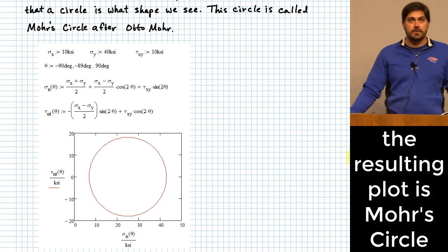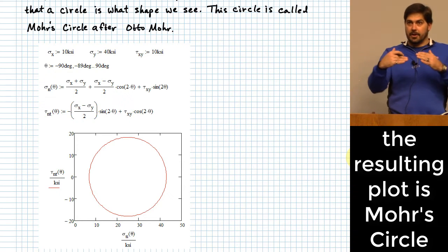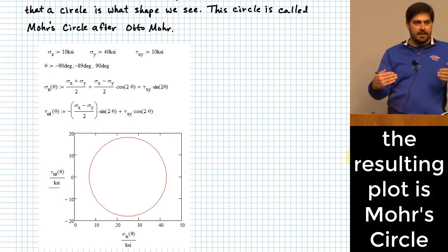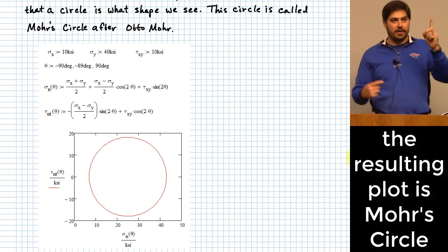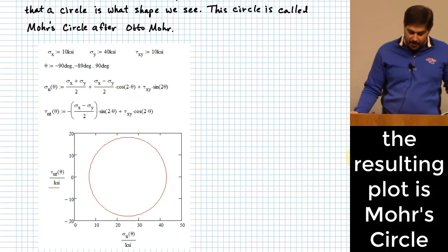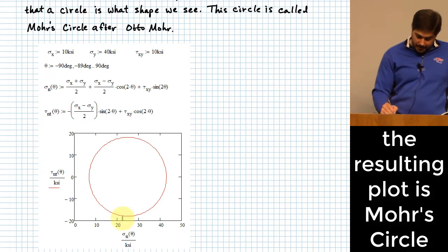Okay, so I took those functions that we just created, right? We went through from the very beginning and figured out what these stress transformations were. And now what we're plotting is shearing stress and normal stress. Shearing stress on the vertical axis, normal stress on the horizontal axis. And we're going to let phi vary through all the possibilities. And what do we see? It makes a circle. Okay? This is where Mohr's circle comes from. All right? And this basically establishes that it makes this entire circle.